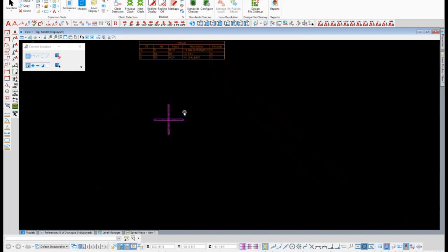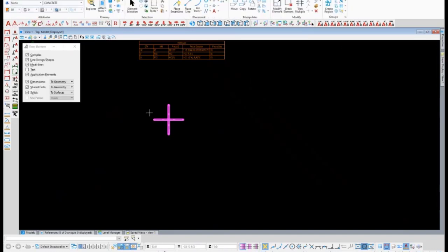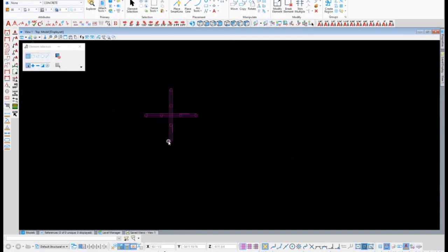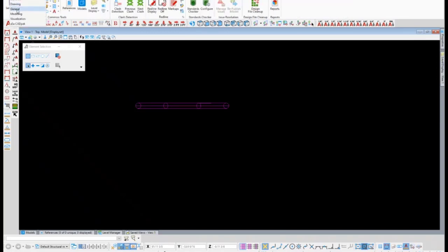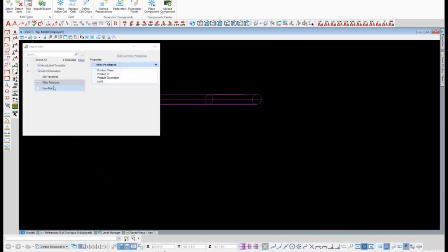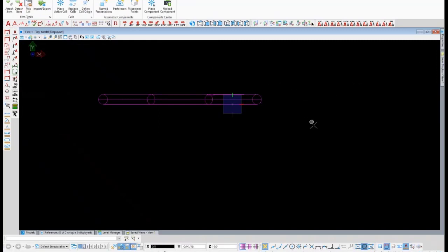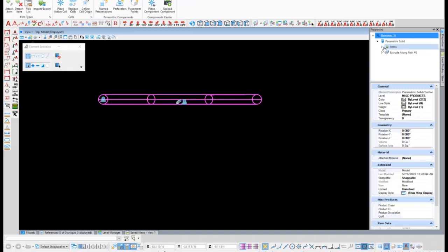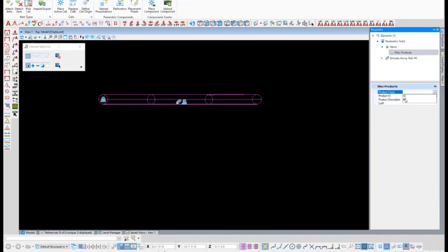And what I'm going to show here, I'll just show you from a simplicity standpoint. If I come back in and I say, all right, we'll go drawing. We're going to drop this guy here because it's a cell. I just dropped it down. Now it's individual lines, right? And I'm going to look at the properties. So this one doesn't have an item type attached to it. So picture that you just drew the item that you want to add as a miscellaneous product, right? And this is how you would add the item type once it's there. So if you have it drawn, all I'm going to do is go to attach. I'm going to tell it it's a miscellaneous product, and then I'm going to click on what I want to attach that item to, close it out. So now if I come back and I look at my properties, I'm going to see an item, miscellaneous, and now I can define what I want that to be.